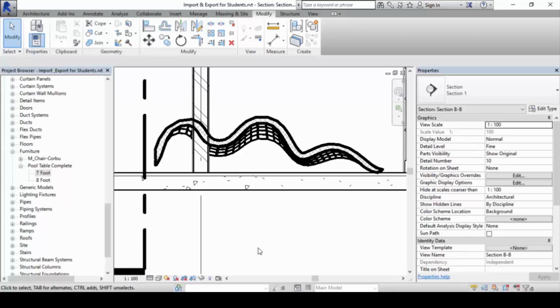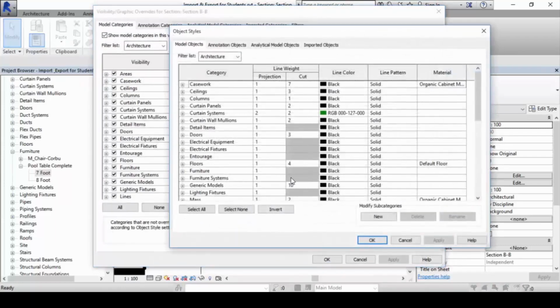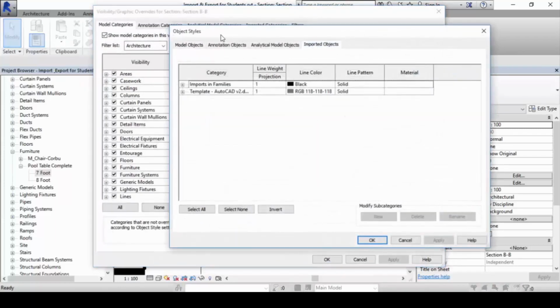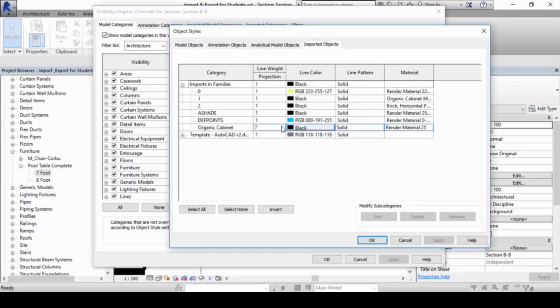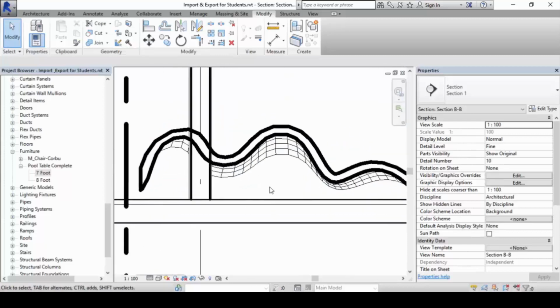Okay, the lines also become thick and everything. So that gives you an idea where you are actually setting the controls. Where can you create the controls for those things? Come, let's change this one back again under object styles. Change it back to line type 1 again, so that it becomes a light line at the back.